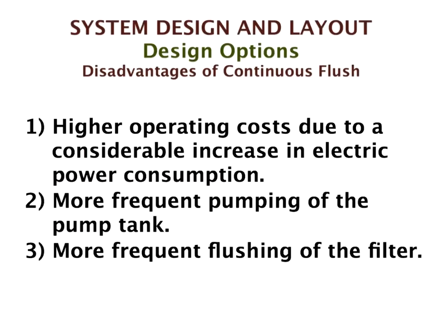However, if you're continuously flushing, you're pumping more water round and round. And that's going to cost considerably more in electricity power consumption. When you pump more water, there is a greater volume of water, so the amount of power consumed is virtually proportional to the volume of water. And then, because you're running at a higher velocity through your drip lines, you're going to have a higher energy loss through friction in the drip line, so that will also increase the electrical power consumption.